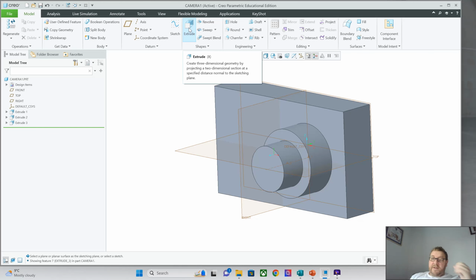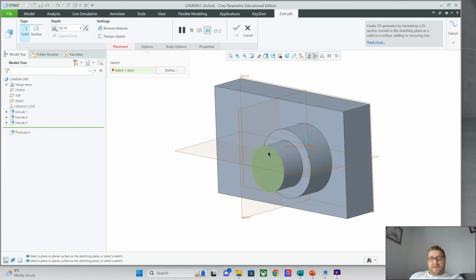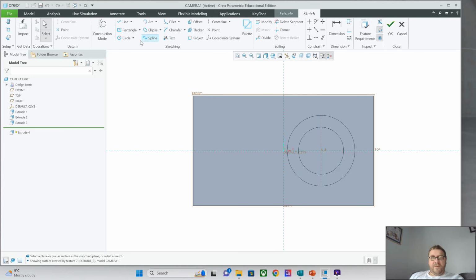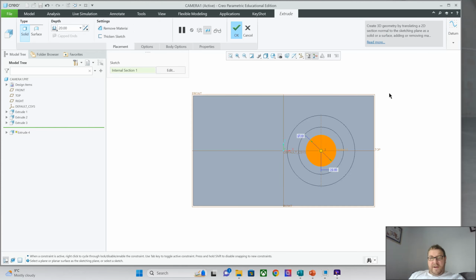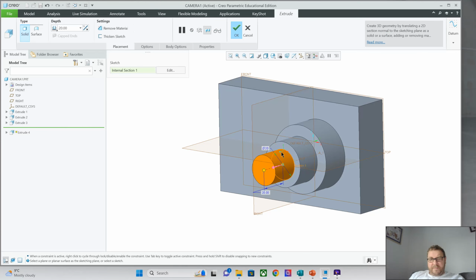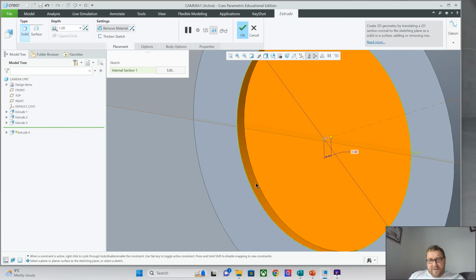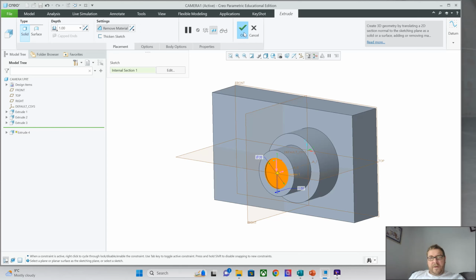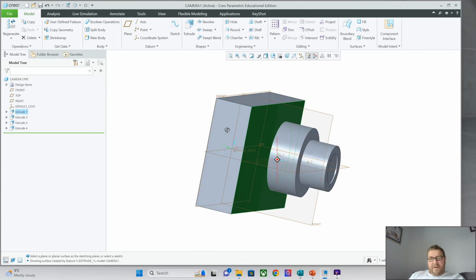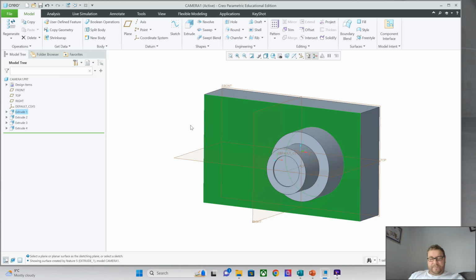The last thing we need to do is actually just click on this surface again. So it's the third time we're doing this. And I'm going to put on another circle. The last one was 30. We'll do this one 20. I'm going to press OK. Spin it round. But watch what happens this time. I'm going to drag it backwards. So I've just got a little lip there. Press OK. And we've created the lens of our camera.